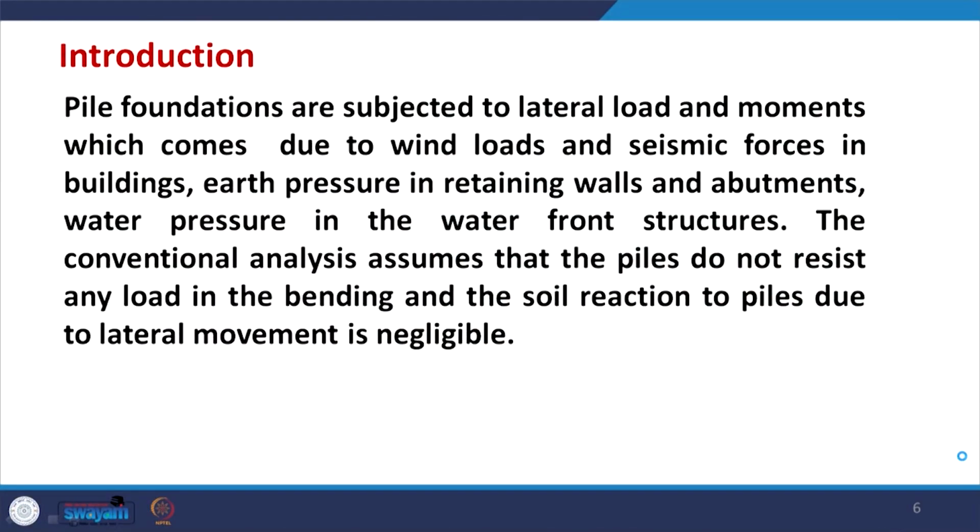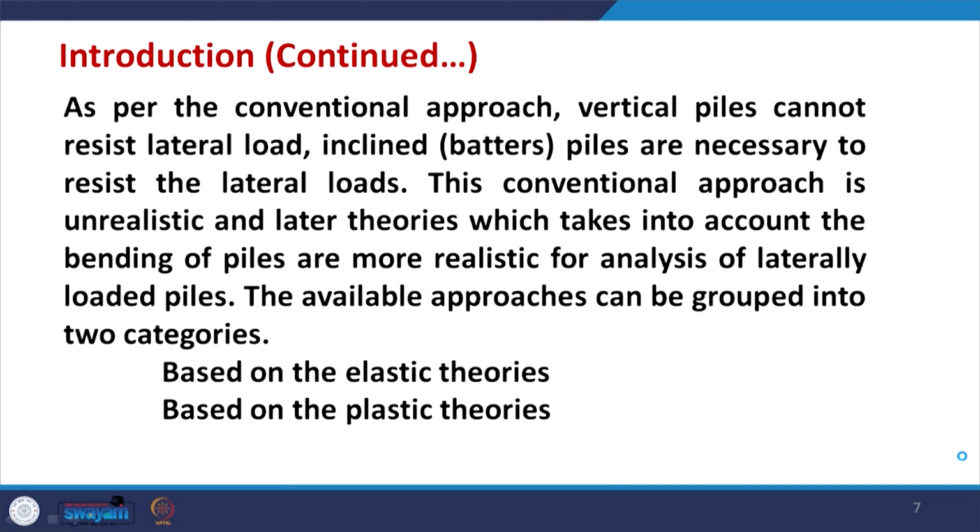The conventional analysis assumes that piles do not resist any load in bending and that the soil reactions to piles due to lateral movement are negligible. That means the flexural rigidity of the piles is not considered, and the piles will not be able to carry the lateral load. However, according to this conventional approach, vertical piles cannot resist lateral loads, and as a result inclined piles, or what are called battered piles, are necessary to resist the lateral loads. But this approach is unrealistic.